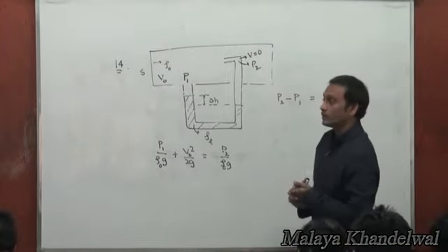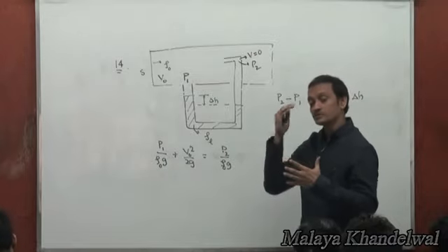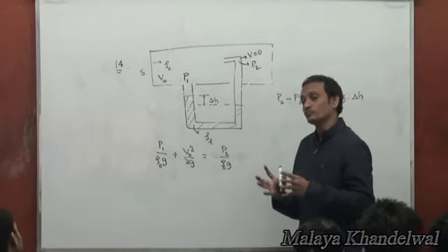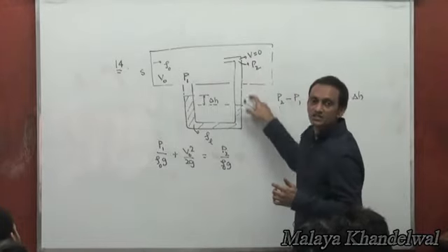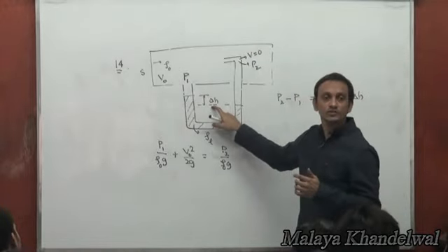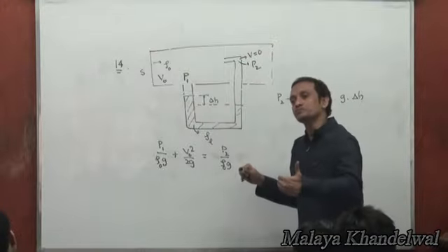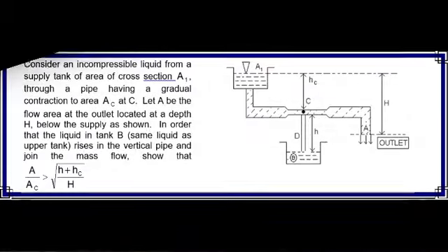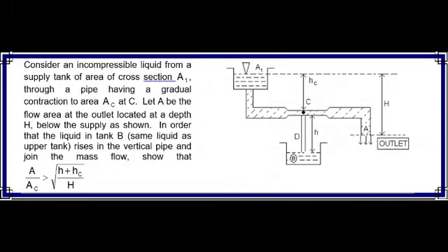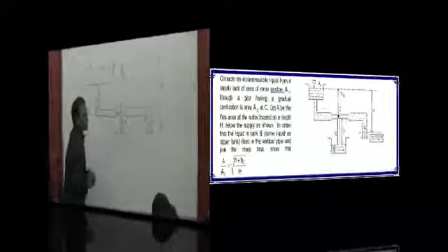I mean, in combustion arrangements, when they want to find the volume flow rate through a pipe, this is what they do. They connect a U-tube like this and measure this delta H, and from there they can readily compute the volume flow rate through the duct, right? Basic idea here.